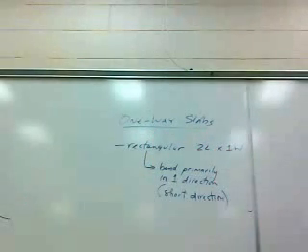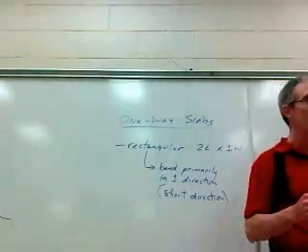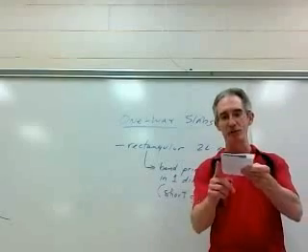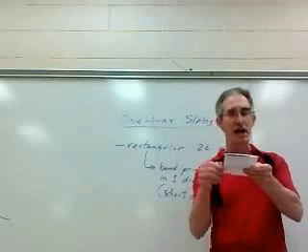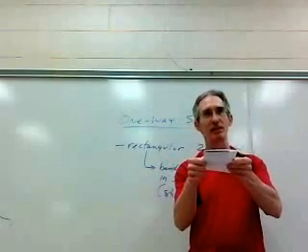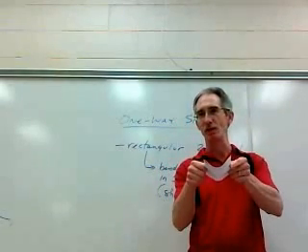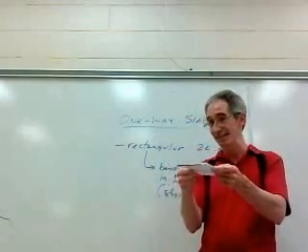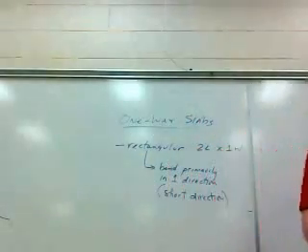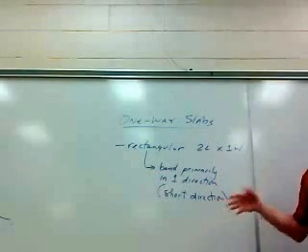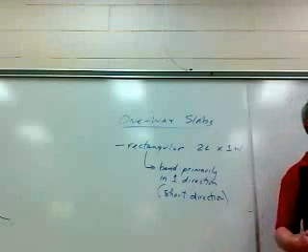And that's not too much unlike, if you had a piece of paper, if you could imagine this, that was rectangularly shaped, and then you had supports on all four sides, and you put a load on this, how would it have a tendency to bend? Well, it'd bend like this, right? It's bending across the short direction. So it's almost like what we're talking about with a concrete slab. So everything holds true. All the formulas that we talked about previously, they all hold true.